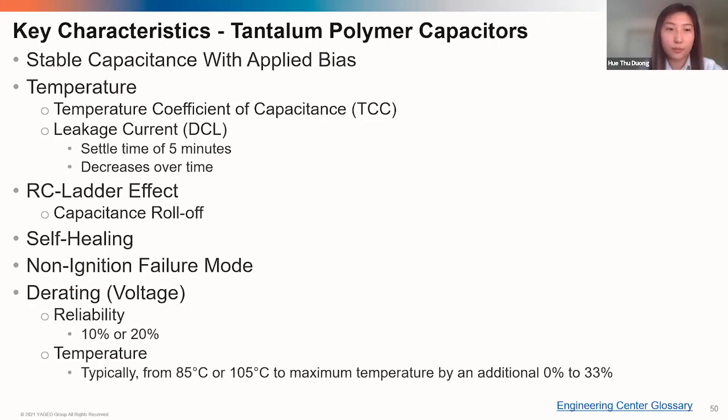And compared to its predecessor, the tantalum MnO2 capacitors, these tantalum polymer parts have a non-ignition failure mode, as seen historically in tantalum MnO2 parts, where those parts would have an ignition failure mode. These parts do not have that because they don't have the MnO2 technology in them.